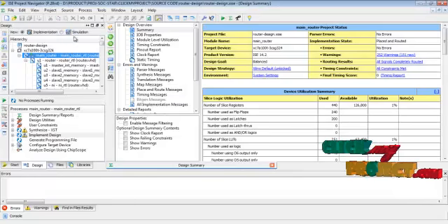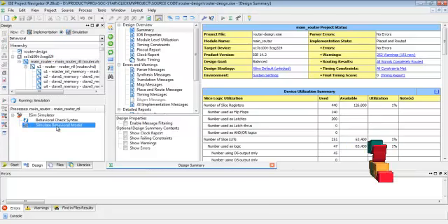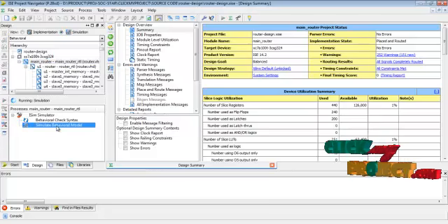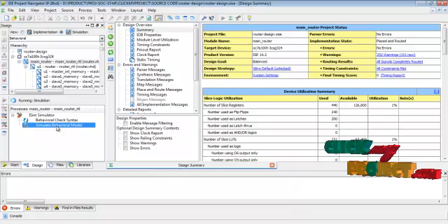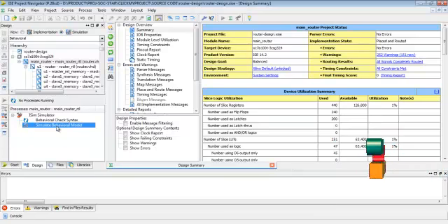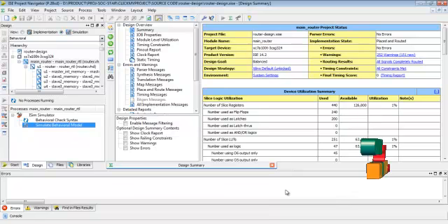Next, select the main router function and the simulate model, then run the simulate behavioral model for the overall NOC architecture design. Then create the Xilinx ISim project. This ISim project is mainly used to simulate our overall NOC design. We apply the binary input data for the NOC input and get the output for the star-based NOC architecture designs based on our selection line.